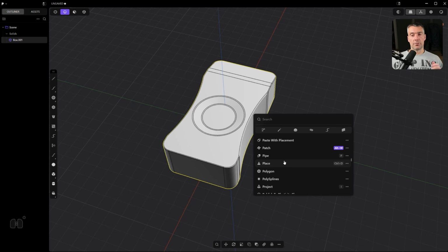So if it's a conflicting shortcut in the same state of the mesh, you're going to be in trouble. But if, for example, one of them can be activated only when the mesh is solid and the other when you're in the edit mode, let's say in edge mode, then you're fine. But if they're going to be activatable in the same state of the mesh, you might want to avoid this because it's going to be conflicting.